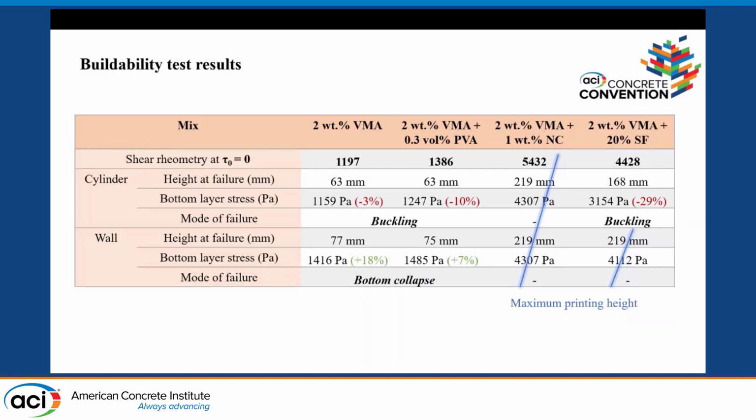And the silica fume was the one that's interesting. I was able to record this with less than 30%. So that huge reduction in my shear modulus was actually meaningful. That imposed stresses on my layers actually did decrease my shear modulus, and that was the reason I was starting to see local buckling effects come into play.